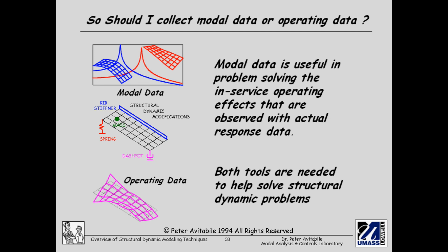But sometimes the operating data is confusing, and it's not clear-cut as to which mode or modes are primarily causing the total response problem for your system. In those cases, then I want to collect modal data in addition to the operating data, so I have a better understanding of what the modes are, so that I can then make some structural changes or fixes to the system.